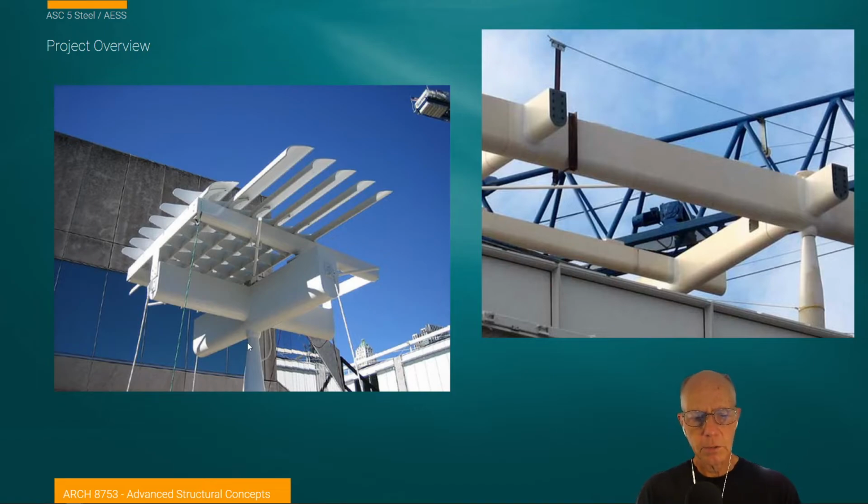We're not at that level of structural engineering to really understand that, but this shows you the level of detail and quality of the exposed structural steel, the fit and finish of all of the components coming together. These modules go up on the building this way, and then there are hidden connectors that join these elements together. I believe this one's a mock-up because of the way the ends appear, because on the right we can see bolt connections in black for the joining of one element to the next.